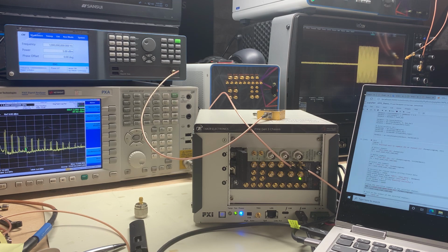So when we talk about up conversion, I'm going to talk about how we can utilize some of the other Nyquist zones, but also take advantage of the interpolator in the system as well, and the digital up converter that we have to be able to create some more spacing, just make the signals a little more spectrally pure as we get higher up in frequency.